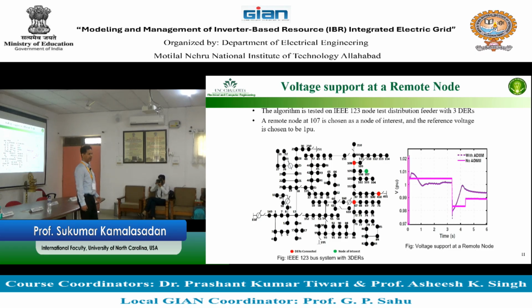What do you mean by Thevenin impedance? You're looking at a point right here and observing the voltage and current. From the voltage and current, you derive an impedance, which is a fictitious impedance, not the impedance of the line, but the impedance seen at a specific point of time.